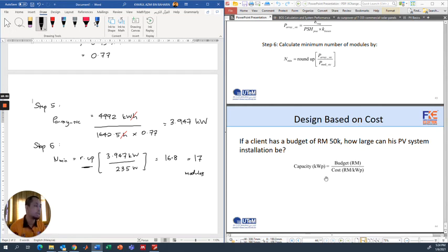It's used to describe PV modules because the capacity is the peak value, the maximum that can be reached by the PV system. In actual practical application, the capacity is going to be reduced because of the losses embedded in the system. The losses are surely going to happen, but this is the representation of the peak capacity.